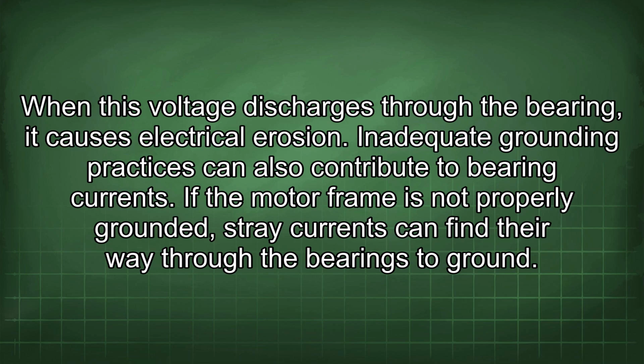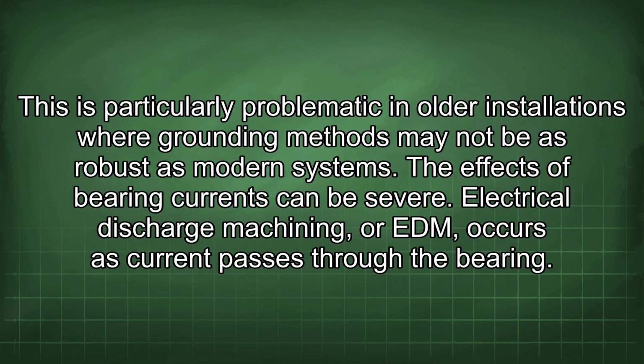Inadequate grounding practices can also contribute to bearing currents. If the motor frame is not properly grounded, stray currents can find their way through the bearings to ground. This is particularly problematic in older installations where grounding methods may not be as robust as modern systems.